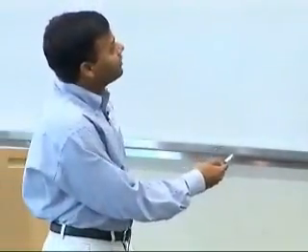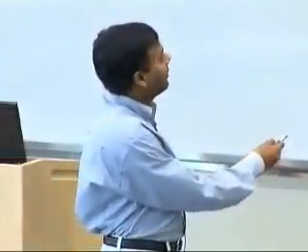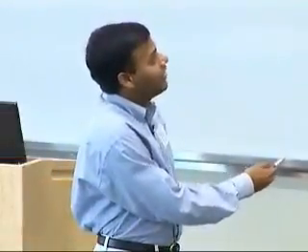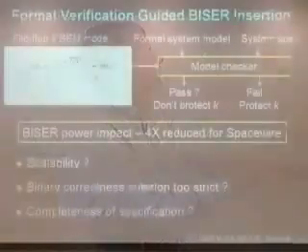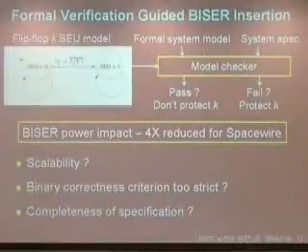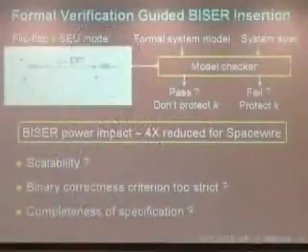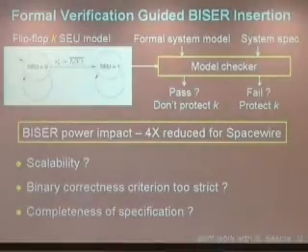We were saying that, look, what's going on over here? If you have a bunch of flip-flops, and let's say you were worried about a soft error in a flip-flop, you could model that as a 2-state finite state machine. So there was no soft error to start with. At some arbitrary cycle, a soft error happened, and from that standpoint, there is no other soft error that would happen. Everything would be fine with that flip-flop. And now, if you just take a cross product of this particular 2-state machine with the formal model of your design, you can check for properties of the design, and then you could come up with 2 answers. If the properties pass, then you don't have to protect that flip-flop. Otherwise, if the properties do not pass, you do have to protect the flip-flop.